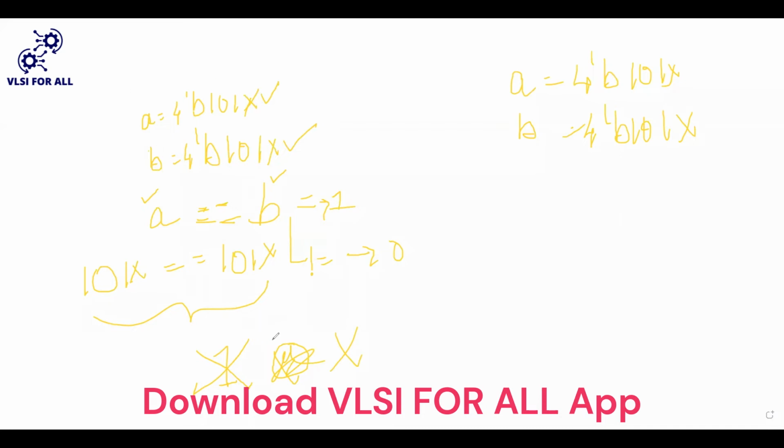Yes. So it will reflect a value of don't care, because it cannot compare the don't care or the z values. As it cannot compare, it gives us a result that it was not enabled to compare. So to overcome this problem, we will go with the case equality. What does case equality mean? If I'm using the case equality, it will compare bit by bit, and whenever the bits are one and the same, it will give the value of 1. And if these variables are not the same, if A and B are not the same, then it will give the value of 0.